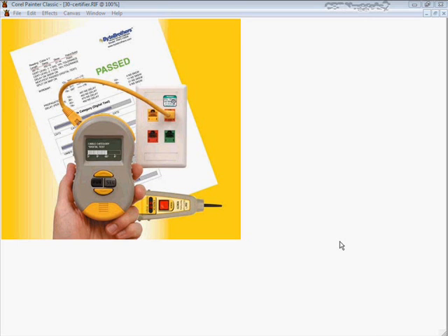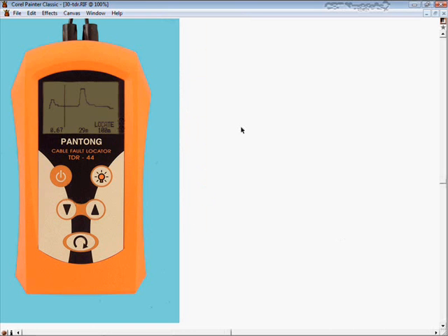These can do speed testing. They can test for and report on cable propagation delay, cable skew, and they can operate with different types of cables: Category 3, Category 5, Category 5E, and Category 6. These can also port the output to a laptop or a PC, so you can save the test and print the test, kind of similar to what that network analyzer, the protocol analyzer, can do that we just showed you. Certifiers.